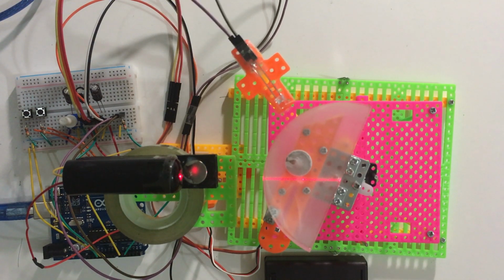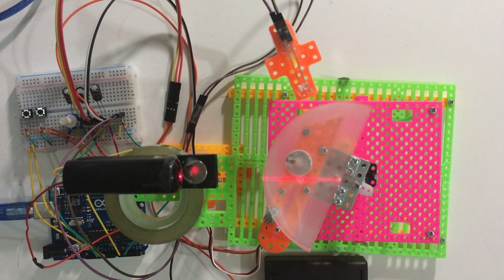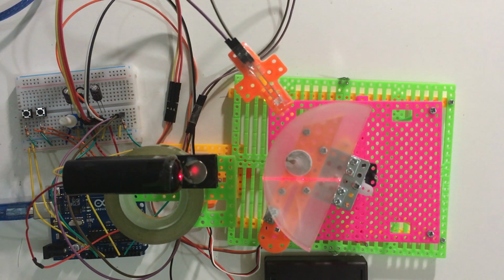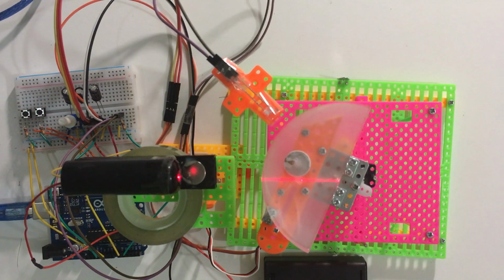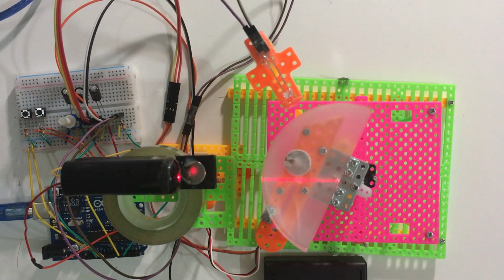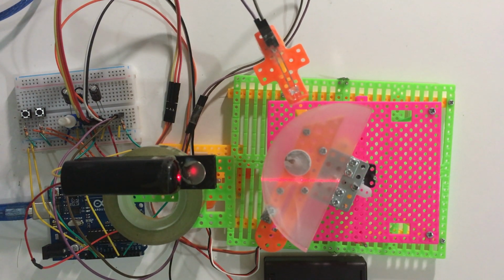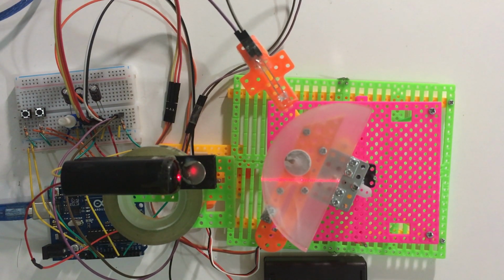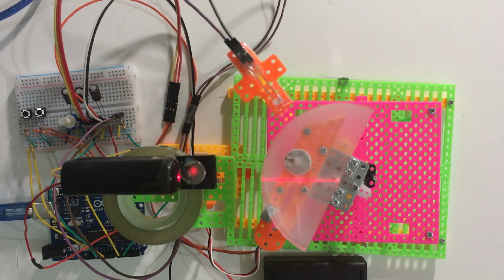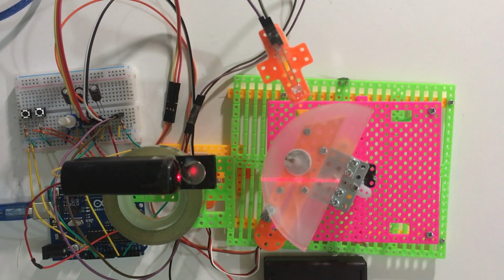I've tried 0.5 degrees as the interval, but the lower servo often shakes, and it couldn't work for 0.2 degrees. When it moves backward, I don't let it take data because it tends to shake sometimes and may result in unreliable data. If it immediately turns to the next lower limit angle after reaching the upper limit angle for the current incident angle, the abrupt movement will cause the servo to keep shaking around. So I just coded it to move back with a slightly bigger interval to avoid shaking and save time.